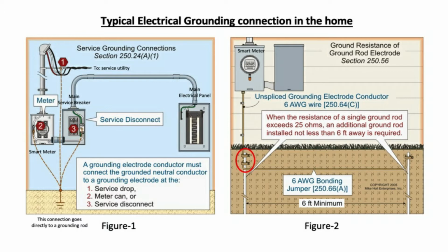And this image shows how that is typically done. If you look at the image on the left, you can see a few things going on. On the right-hand side, there's your main electrical panel, which would be down in your basement, for example, if you live in a home. Coming out the top of it, there's a conduit going over to the main service breaker, and that's really your service disconnect here. In most cases, that main breaker will be installed into your main electrical panel at the top, but in this case, it's shown separately. You can ignore that for this portion of the video.